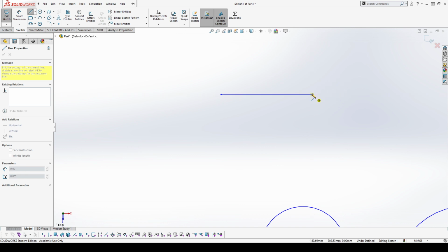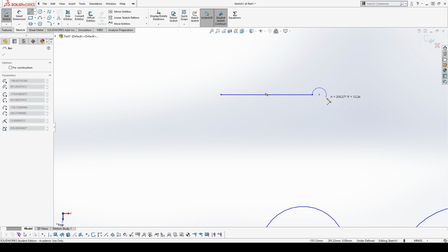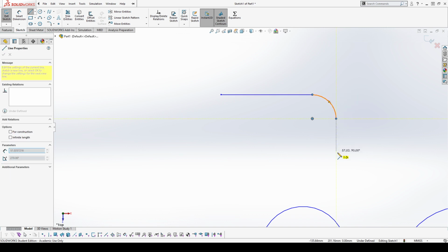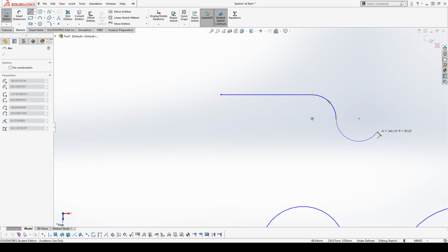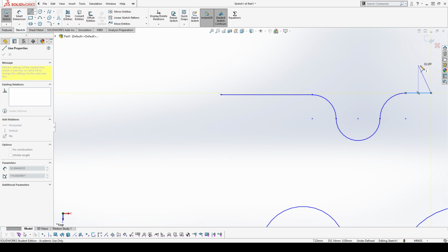So what I do is I go back, hover over the point. You can see that it's going to turn into like a circle icon at the bottom of my tooltip cursor there, and then that's going to show me that, hey, I'm drawing an arc now. Boom, just like that. And then once I start drawing again, it's back to a line. If I want another arc, hover over that point. Another arc, hover over that point. Again, sometimes it's kind of weird and starts to go out other ways, so you just hover over that point. And then you just want to make sure that once you're hovering, you go in the direction of the arc. And then here, and back to lines, whatever else.